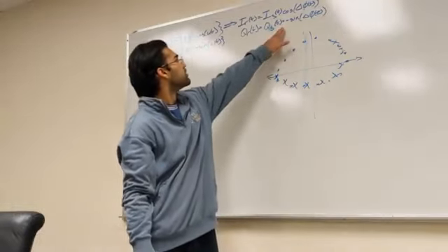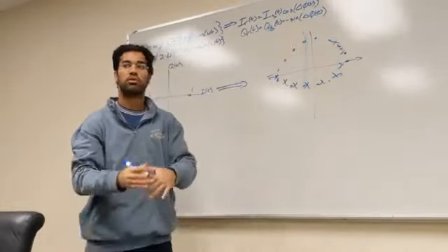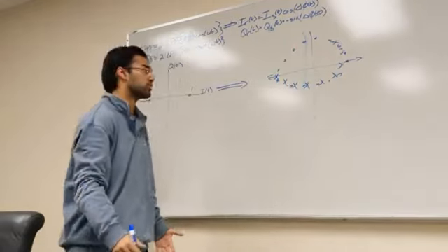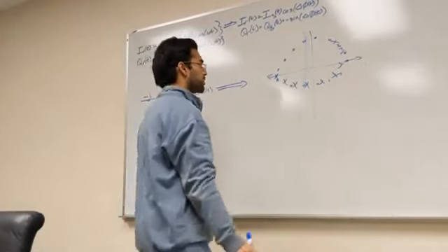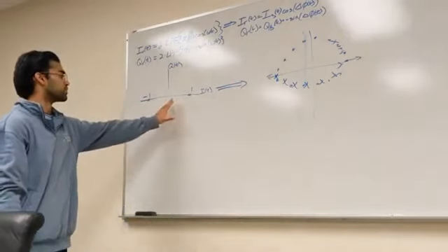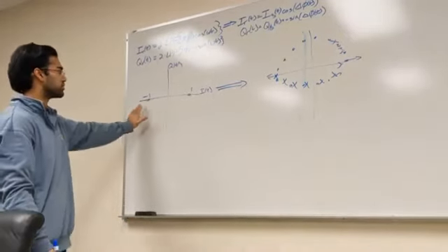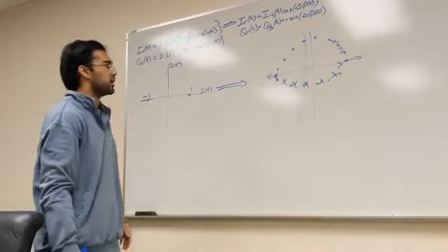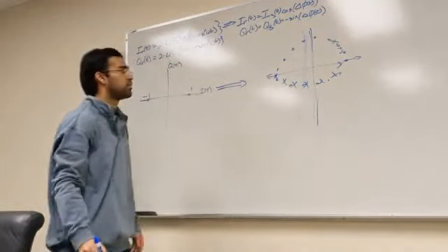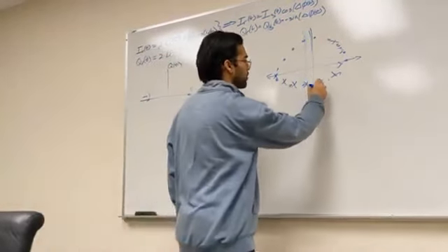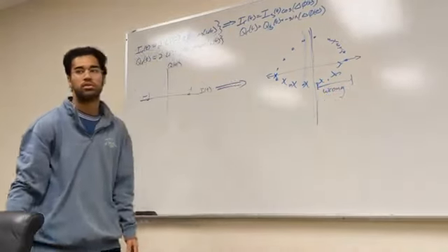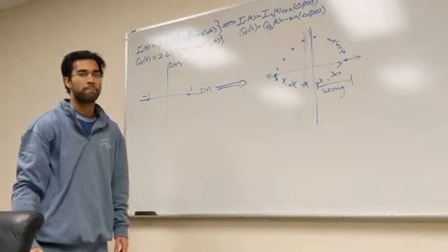Because cos and sine, those are two components of a circle. So when you plot it against each other, it creates a circle. And this is actually very problematic because if you try and just interpret this diagram for the -1 and 1, for your 0 and 1 bit, and you just make your decision boundary over here to decide, then half of your bits probably will be wrong, right? Mischaracterized. So that's quite problematic.